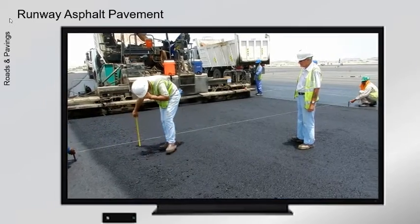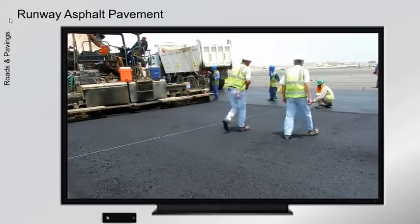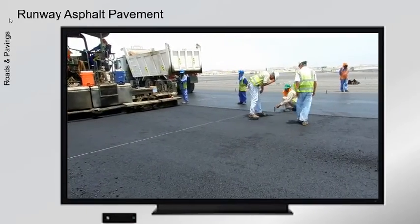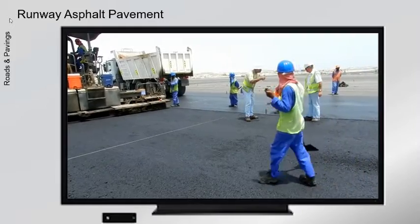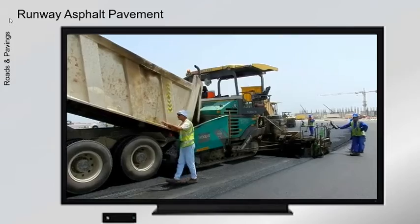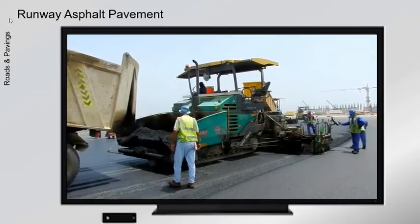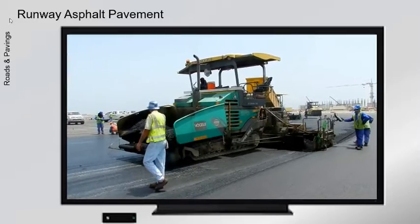Level control is maintained by 2 string lines as a grade reference system for the lead paver and a matching shoe and 1 string line for the following paver. The pavers operate using an automatic screed control, which controls the screed height using the string line or the matching shoe as a level reference.